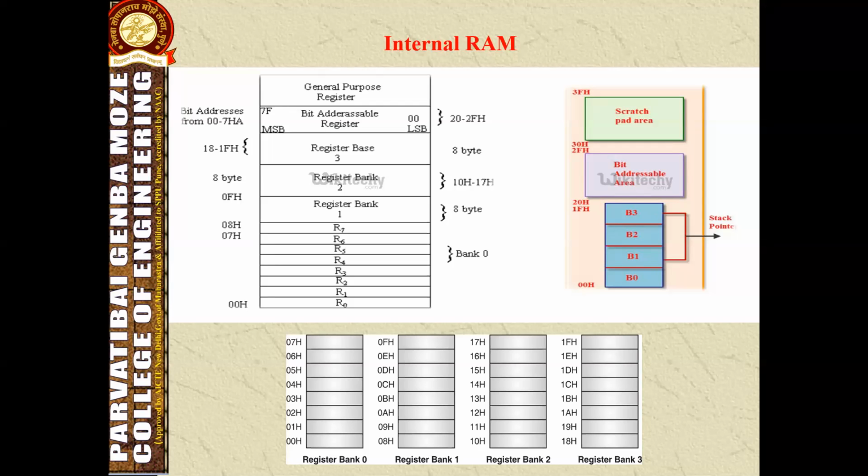There are some disadvantages also. We know that register bank 1 uses the same RAM space as the stack, and this is a major problem. While programming the 8051, we must either not use register bank 1 or allocate another area of RAM for the stack.